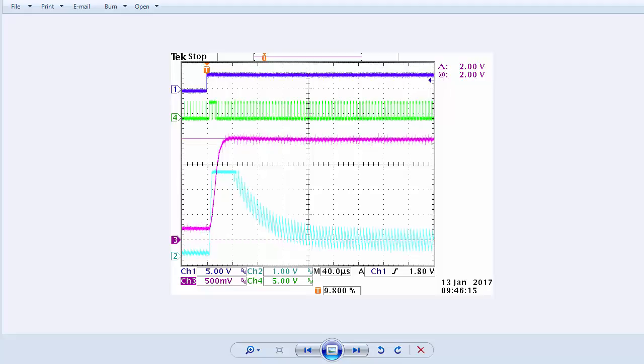This sequence was generated using an automated procedure that ran in system on the target hardware. This is all well and good until you decide to create the compensator and run it closed loop. Now the fun begins. You will have one compensator for startup and another compensator that gives acceptable transient response after the system is on set point.